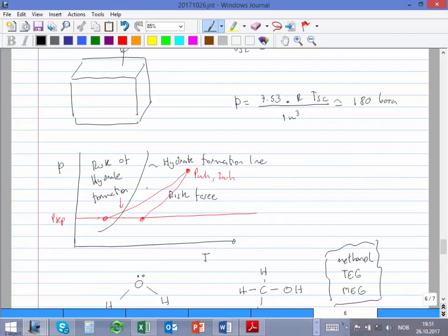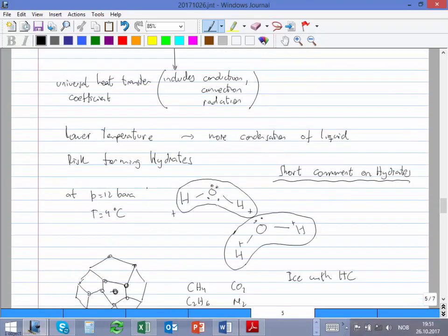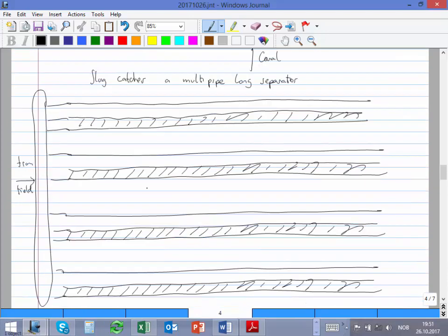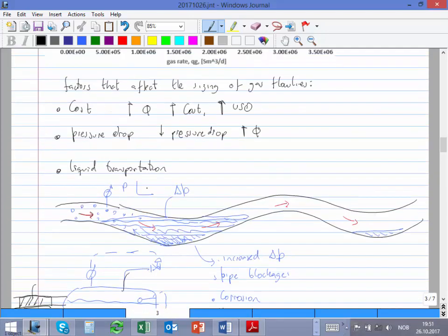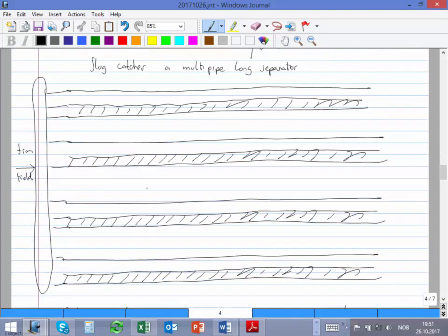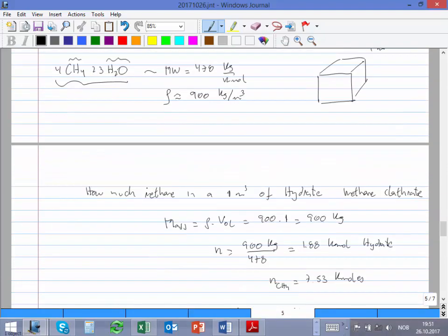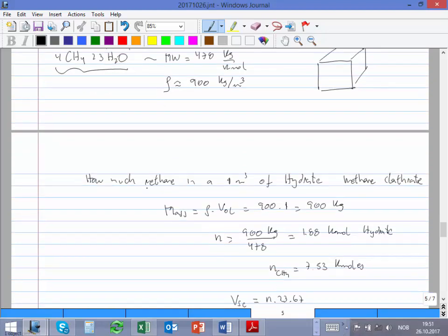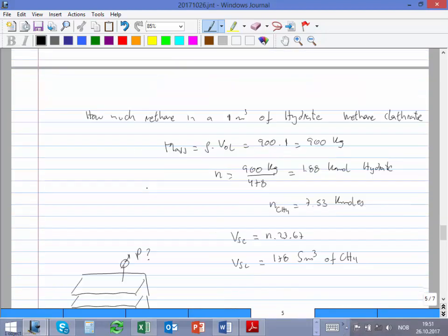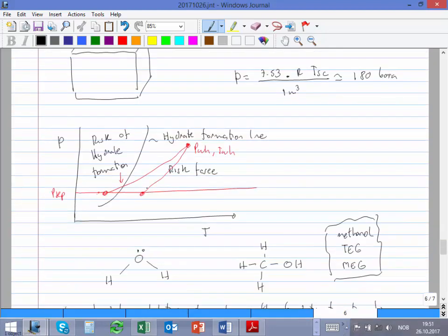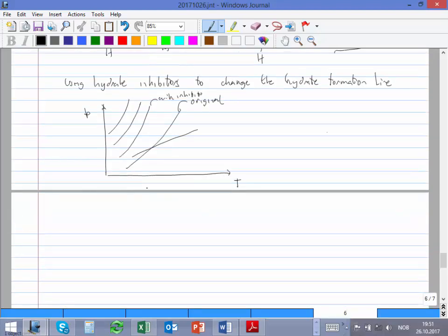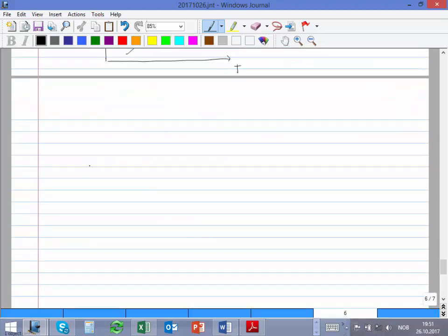So I just wanted to talk about the size of the pipe, and we went into this discussion on hydrates, but basically the cost, the delta P, the pipe has to carry the liquid, and also the problem with heat transfer and hydrate. We want to avoid hydrate. It's not a problem for onshore. It's not a problem for shallow, but it's a problem for deep. When you go deep, it might be a problem. So in that case, you have to inject methanol, and what do you do on the tree?